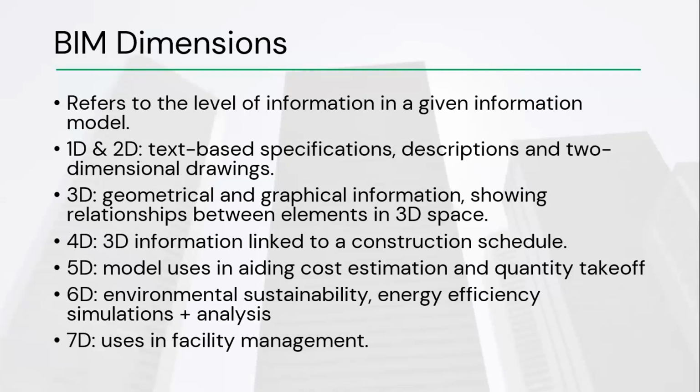But then the 3D model has the floor plans, the elevations, the sections, and the details interlinked, meaning that if you update elements in the 3D view and go back to the other views, the floor plan, the sections, the elevations, you'll find that the update has been automatically captured in those other views. So there is a lot of time that is saved there.